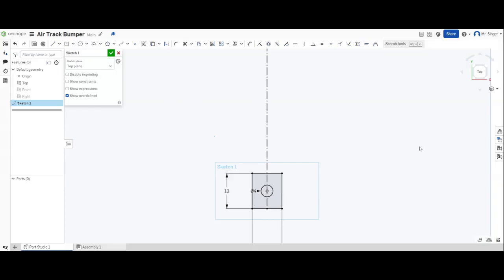Okay, so this line is going to be, because of the way I measured it, 30 minus 12. Now this will show a pretty cool thing you can do with this as far as the dimensions are concerned. I'm going to go to this dimension tool right here. This is where the fun happens. You can set the dimension to 30 minus 12, and it makes it the right length.